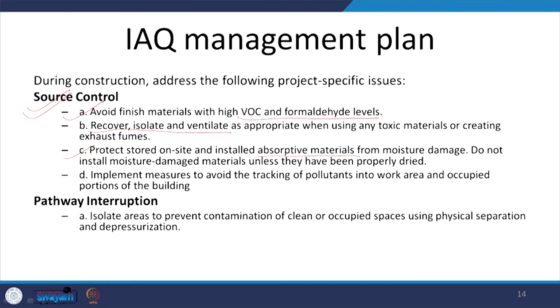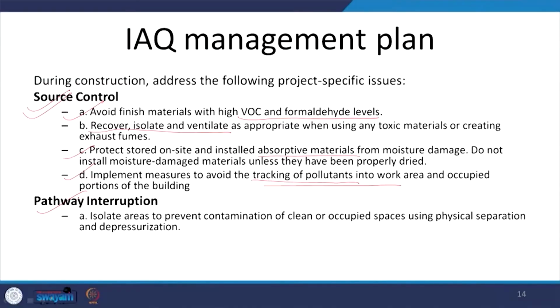And we have to ensure measures to avoid the tracking of pollutants into the work area and occupied portions of the building, if there is an occupied portion of the building and simultaneous construction going on. Also, we have to ensure that there is a pathway interruption in order to isolate areas to prevent contamination of clean and occupied spaces, by providing physical separation and depressurization.